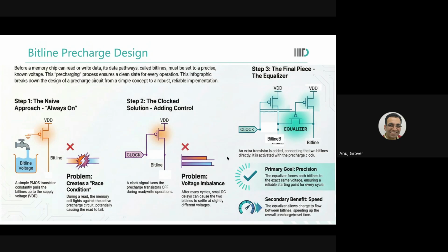We have to increase the offset of the sensitivity. We have to create 2 millivolts extra differential. We have to assume that the sense amplifier has 2 millivolts extra offset. If I do it at 5 millivolts, extra 5 millivolts. So why do we want to play with this 2 millivolts or 5 millivolts over there?